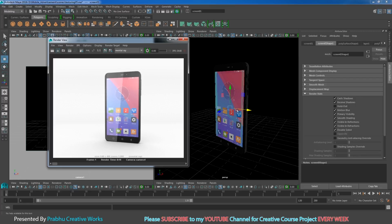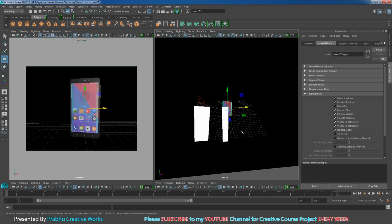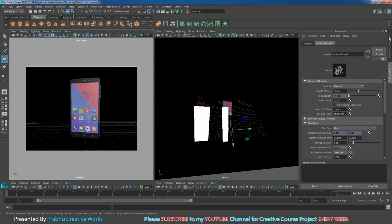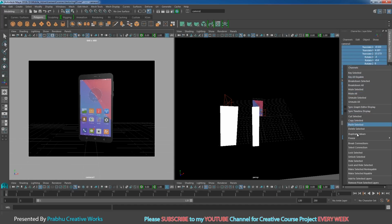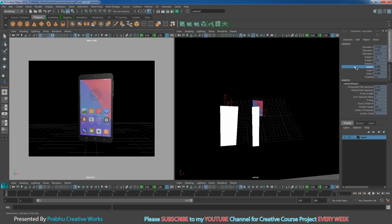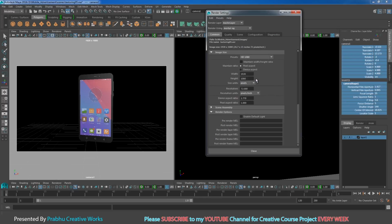So now we finish lighting. So now you want to check in full HD view. So go to view, select cam. So I want to go to channel box and layer editor. So right click on all values for your camera, right click and choose unlock selected. So that means select all my values, right click and choose unlock selected. So now go to render settings. Here you need to go to the common tab. So here you need to choose HD 1080.